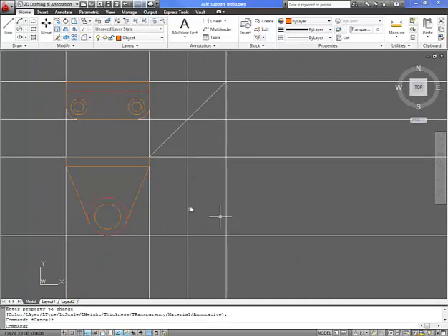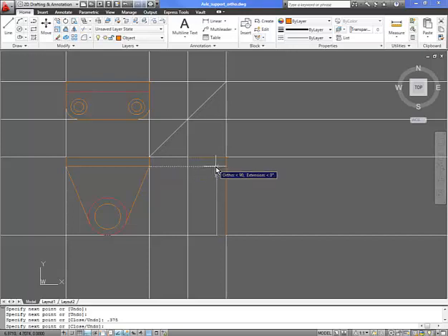Now we're going to focus on our right hand side view right here. So we go line with the object layer. We're going to go from here to here. We know that goes all the way over, and then this one is 0.375. Then it goes up until it meets with this one. So it's right at that point, then comes over this way, and then closes that way. So now we have our right hand side view right here, looking at the object this way.